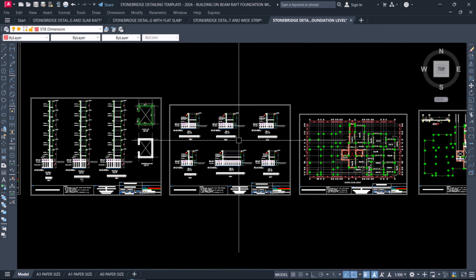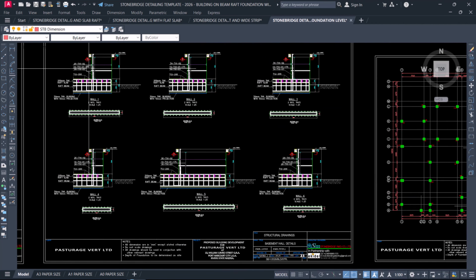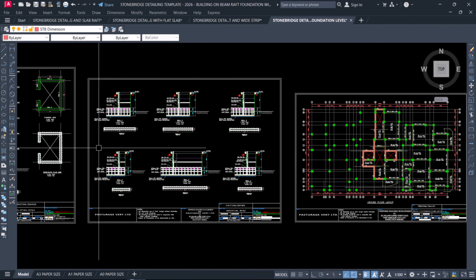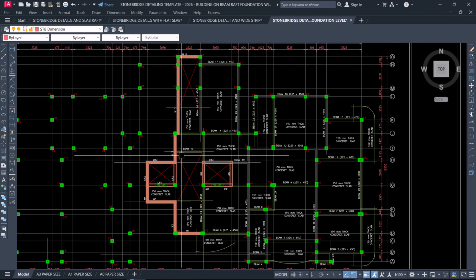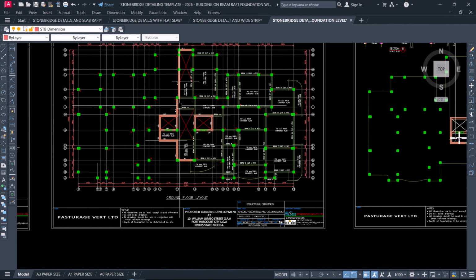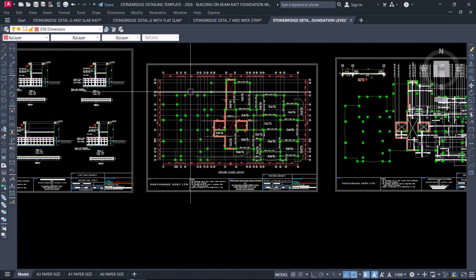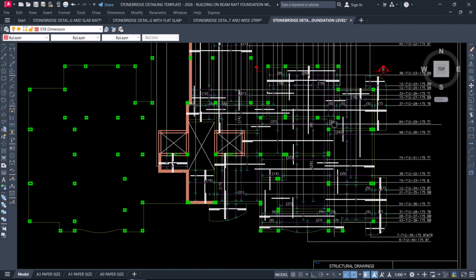And these are sections of the basement wall, because there's a basement wall that separates the two levels together to avoid landslide. So we have these two here. So again, you can see the wall here. This is the wall that separates the two levels, so that the weight on this side will not cause a landslide on this other side that is not the same level. So you have to prevent it with a retaining wall, which you can see here too on how it is being detailed.